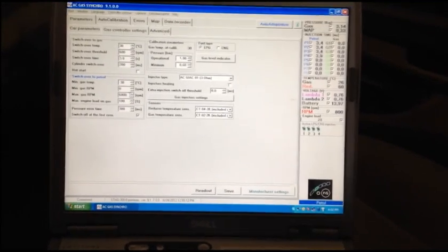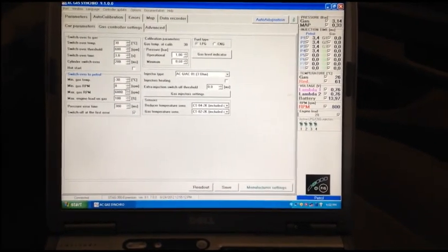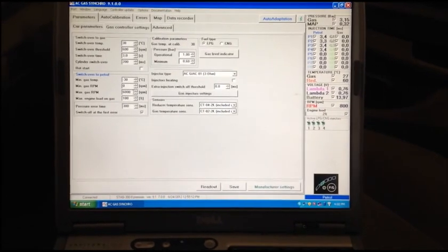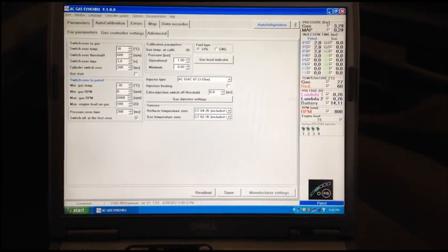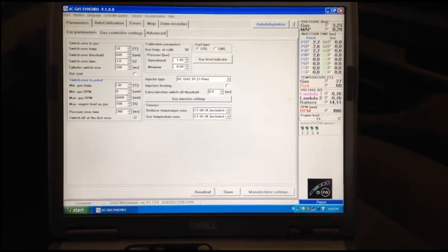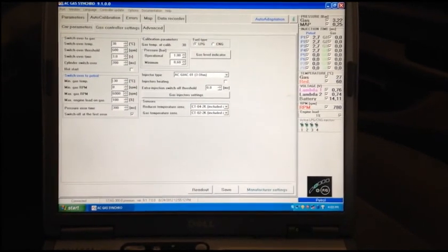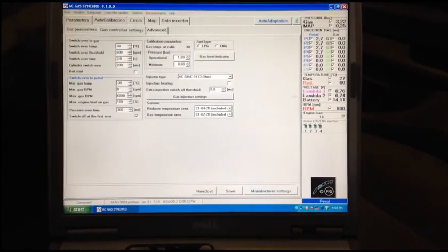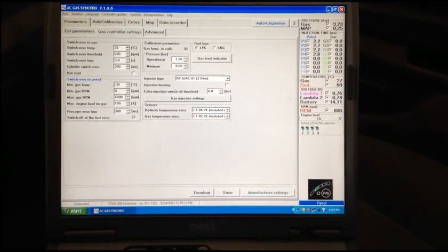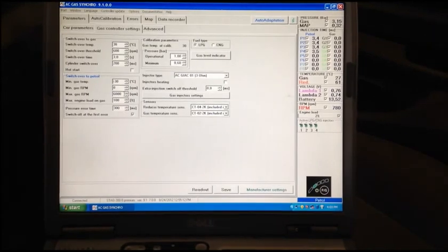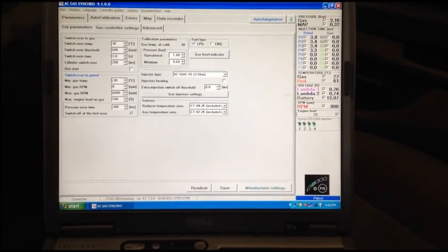You've got your regulator pressure turned up to 2.5 bar, which is the maximum recommended pressure, and really it doesn't do anything turning it up higher than that, and the regulator's not intended for it. But still, at the upper RPM, you're leaning out right before you hit redline. You can set that to 1,000 RPM below redline, just wherever you're seeing your system lean out too much. You can set that there, and it'll switch over to gasoline once you hit that RPM.